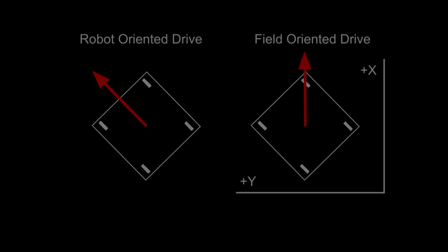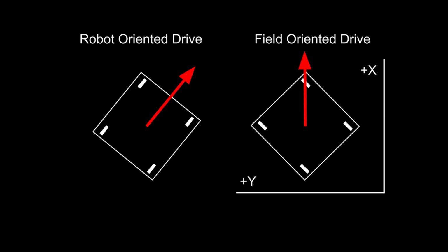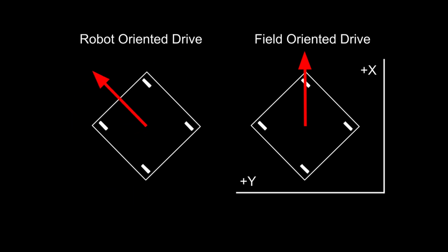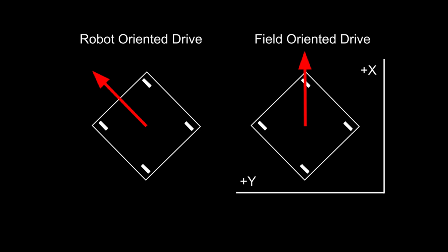Now that our Swerve is driving smoothly, it's time to make our final optimization. In its current state, it's very difficult to turn while moving. This is because all desired chassis speeds are given relative to the robot's heading, which constantly changes when you're spinning. A much more intuitive way of controlling the robot is giving its inputs relative to the field, because then, no matter which orientation the robot is in, a forward input will make the robot go forward in the field. So let's code it.